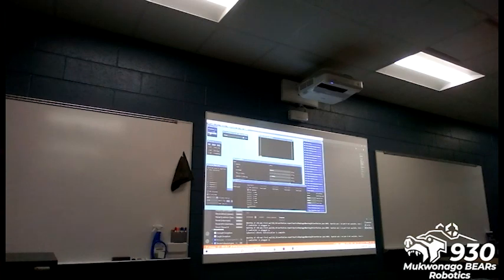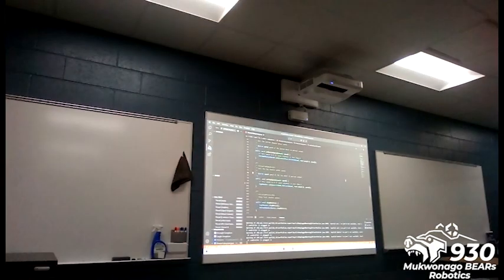I'm going to go into teleop, make sure my controller is in the right spot, and when I hit the button that we have tied to this set top speed, it will hit the breakpoint and stop the code. Here I can either play, which continues the code as normal until that breakpoint is hit again.